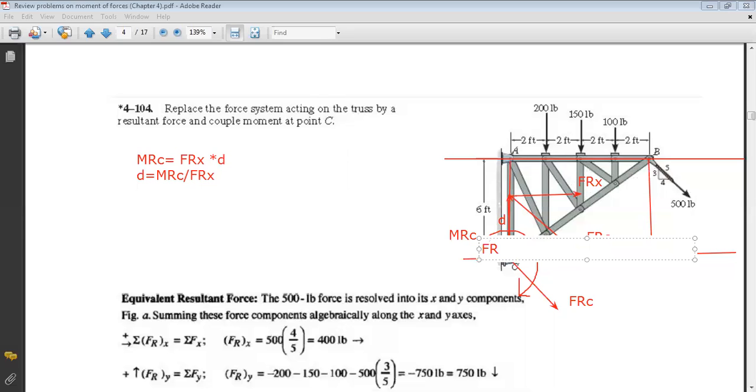So now, when you displace your force, as you can see, since you are displacing it on AC, the Y component will not do anything because look, the Y component is always passing by C, so it cannot produce a moment about C. But what will make the change is the X component, because when you displace along AC, the FRX component will produce a moment about C.